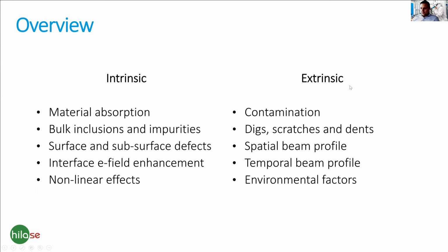However, when we consider extrinsic damage precursors, this is something we can affect by our behavior, by the way we are handling the respective element, or how good a laser we are using when we are exposing the element to the laser beam, or how clean an environment we prepare for our utilization of the laser.